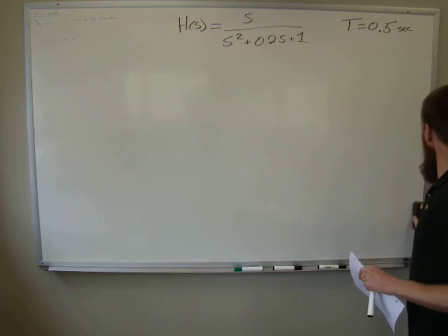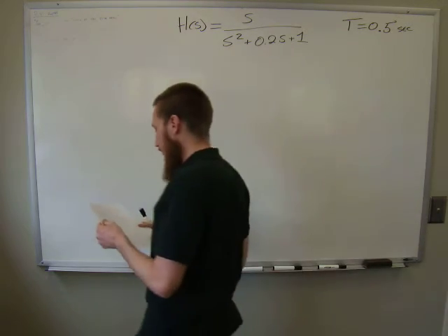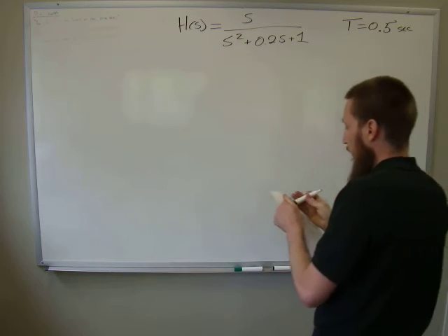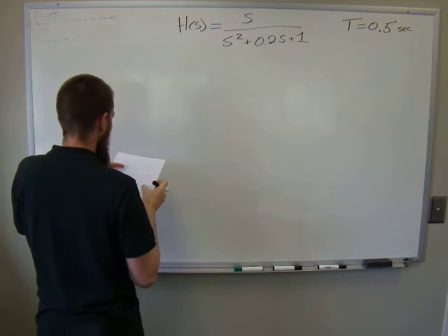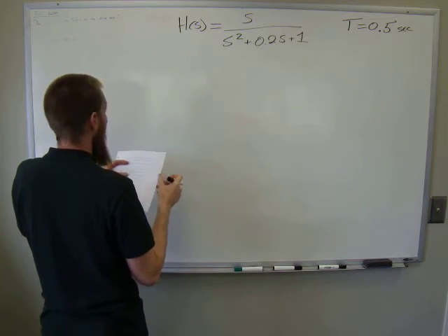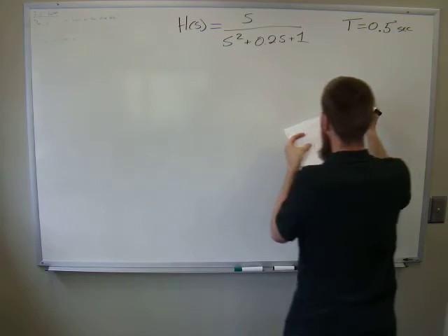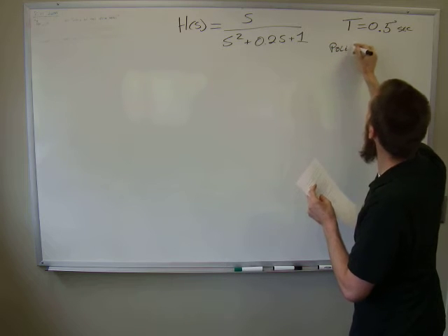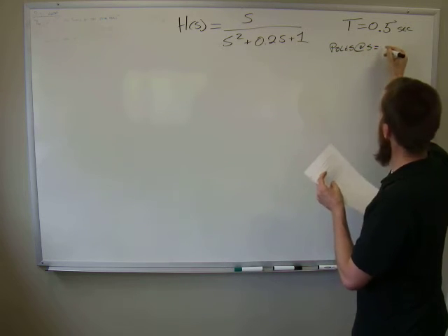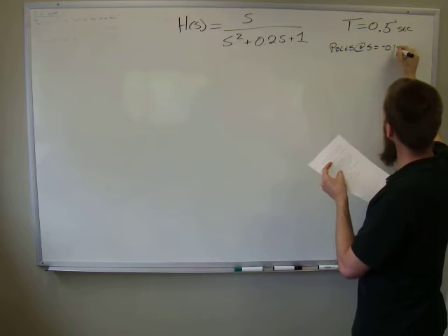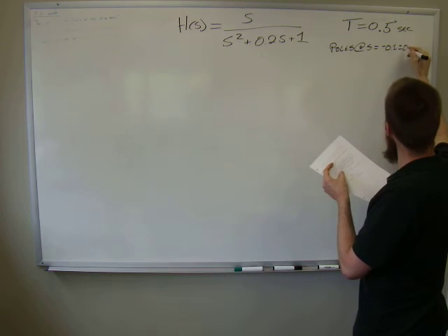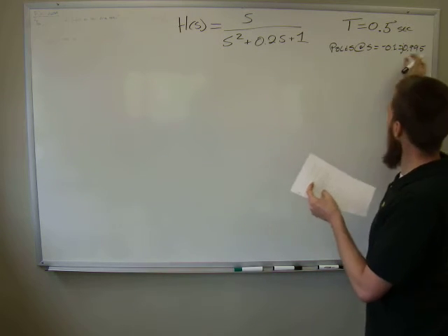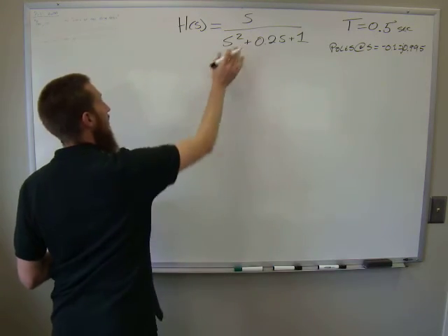So we're going to look at this bandpass filter, try to figure out how to convert it into the other domain. For this one, we can rewrite this, and we can say that the poles of S, the roots of the denominator, are at S is equal to negative 0.1 plus or minus j 0.995. So there are complex poles if we do a solution on the bottom.